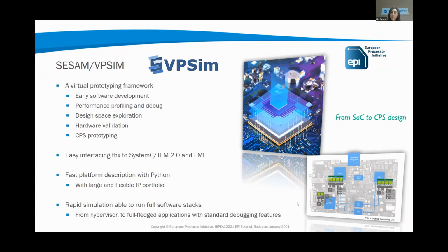VPSim can easily interface with other simulation tools, thanks to SystemC, TLM, and FMI standards. VPSim provides a Python script to describe the platform that we want to simulate, with a large and flexible IP portfolio, and performs a rapid simulation able to run full software stacks.